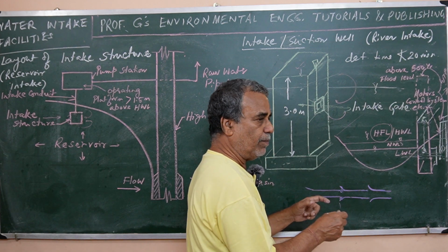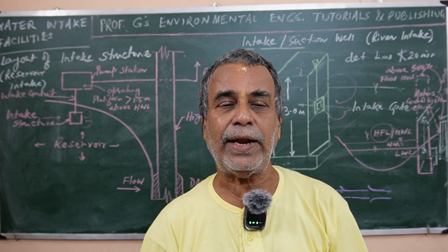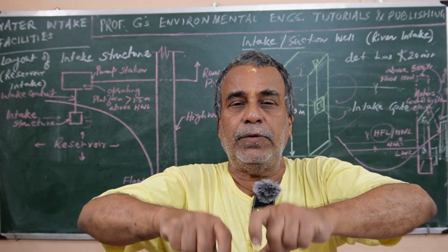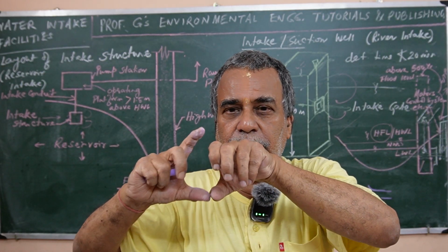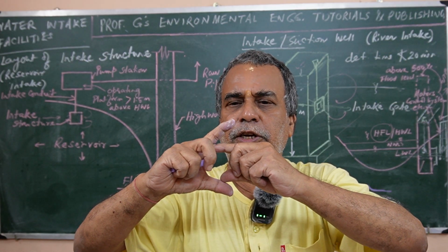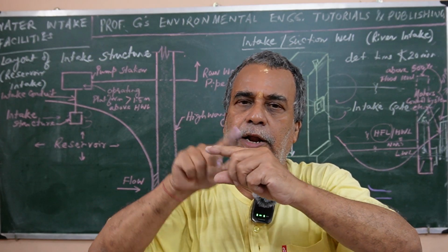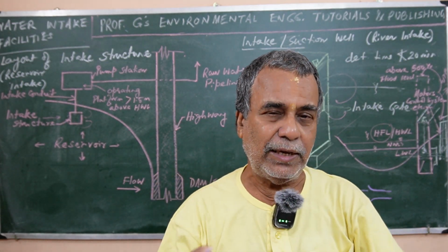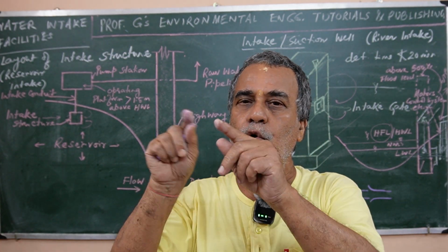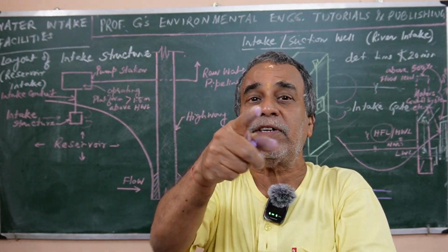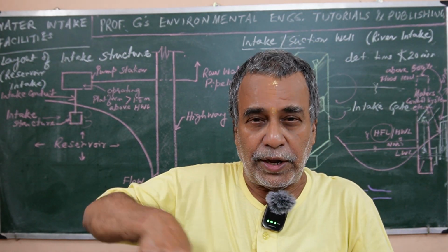Here it should be plugged by jointing materials, like the lead joint, and nowadays the O-ring, high strength PVC, which is just fitted into that. Now suppose this is entering into it, the gap all around the pipe is sealed, earlier by lead joints, and nowadays by an O-ring. It is a ring like in a pressure cooker, if you have seen one.